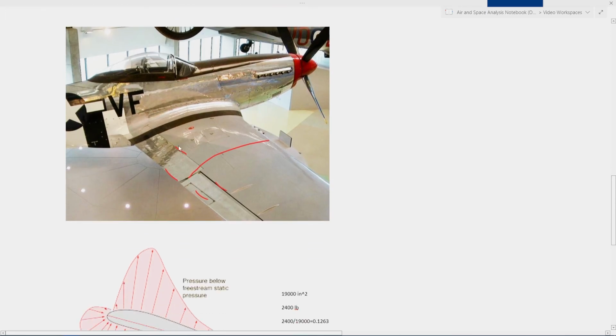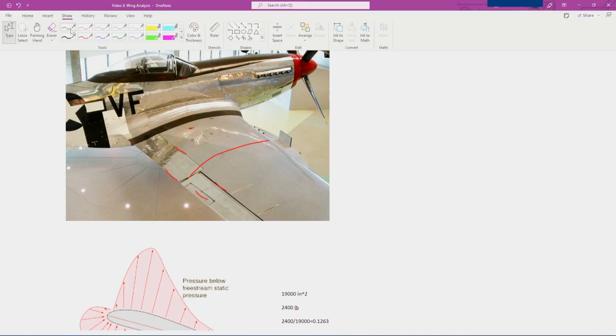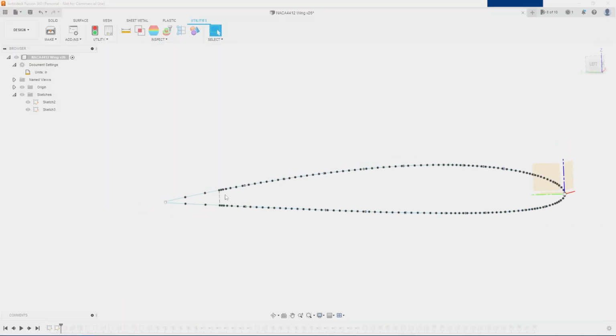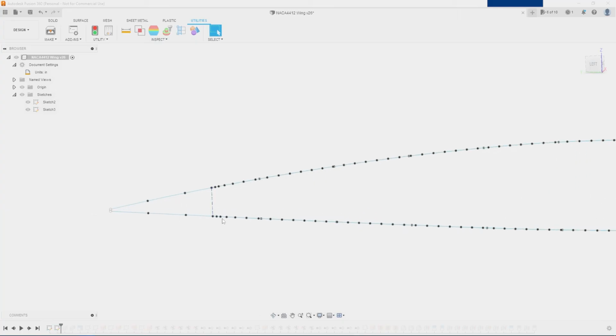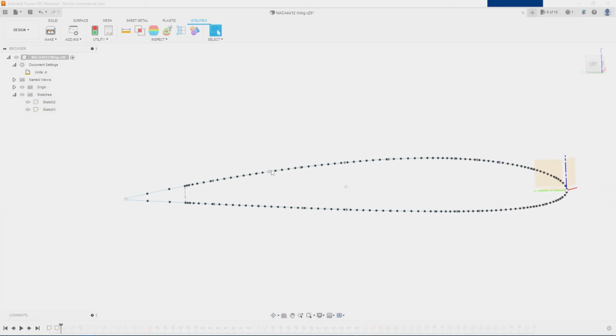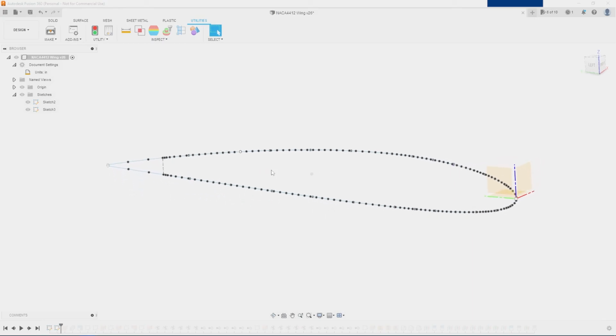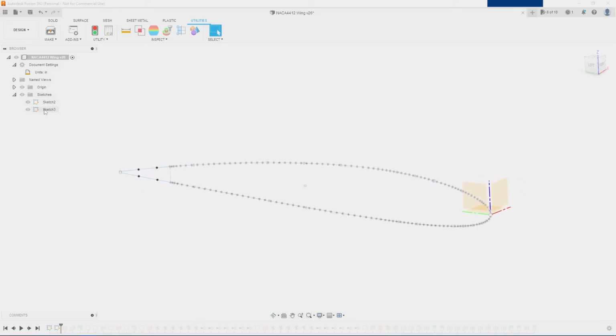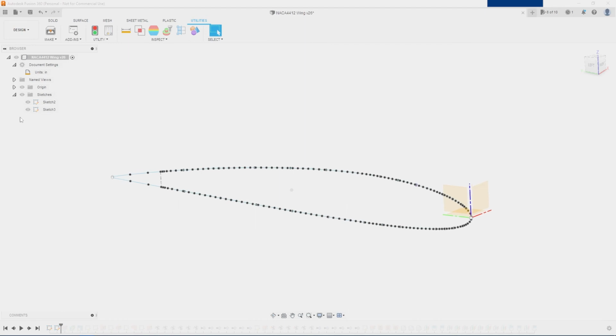So this is kind of where the main wing structure ends. Right along here, the main wing structure ends. So I'm just going to cut off the airfoil shape right here and omit the flaps and ailerons in my analysis, since they're not going to significantly stiffen the wing structure. They're not vital to the structure of the wing since they move.